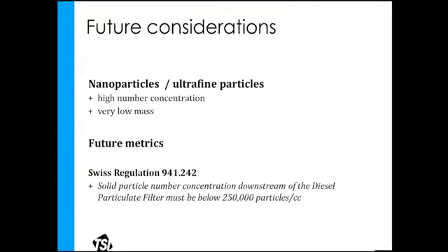There was one regulation. Switzerland is kind of like the California of Europe. California implements tighter air regulation, and the rest of the country follows later on. Switzerland has issued a law. This is for diesel particulate monitoring for fixed sources like the big generators and off-road trucks and mining. So when they're digging tunnels, there's a filter on there, and they have a regulation now that you have to test the filter twice a year and make sure you're not spewing out more than 250,000 particles per cubic centimeter past that filter. So if the filter's working, it's clean.